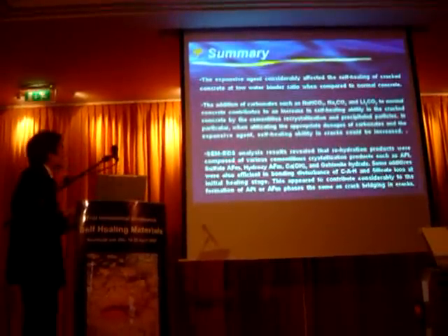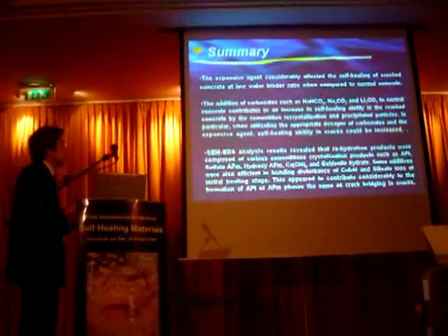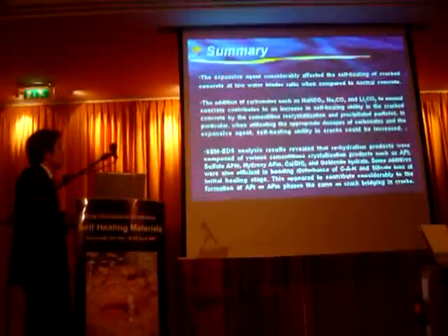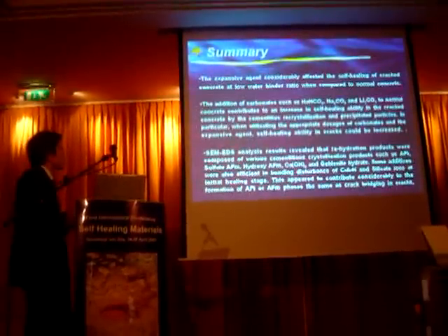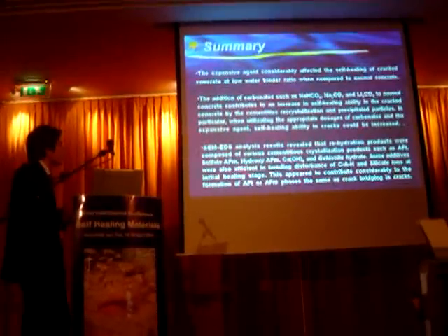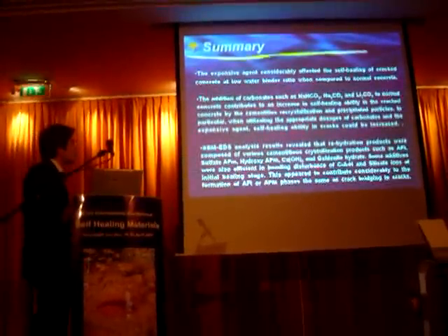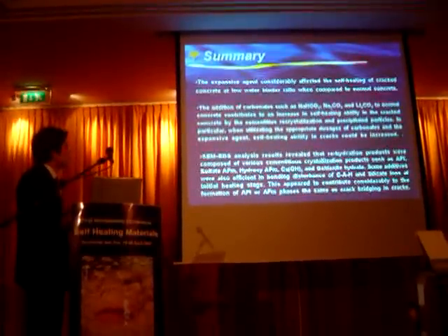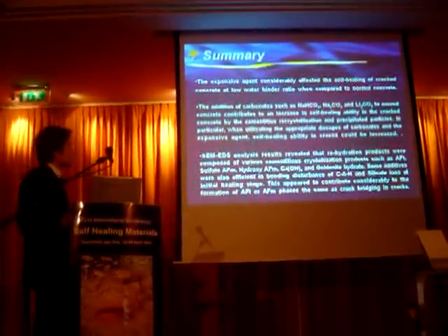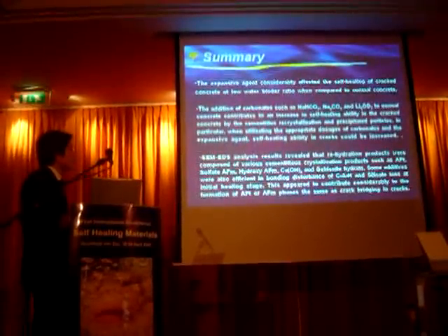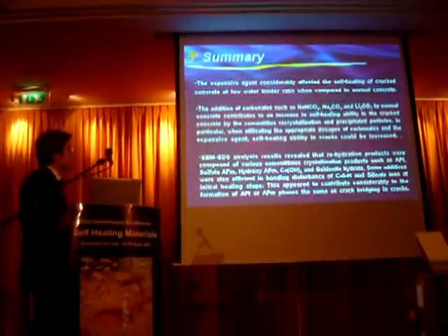Thirdly, analysis results revealed that rehydration products were composed of various cementitious crystallization products such as AFt, sulfate AFm, hydroxy AFm, calcium hydroxide and hydrate. Some additives also acted in the bonding disturbance of calcium hydroxide and silicate ions at the initial healing stage. This appeared to contribute considerably to the formation of the AFt or AFm phases, the same as crack healing in cracks.